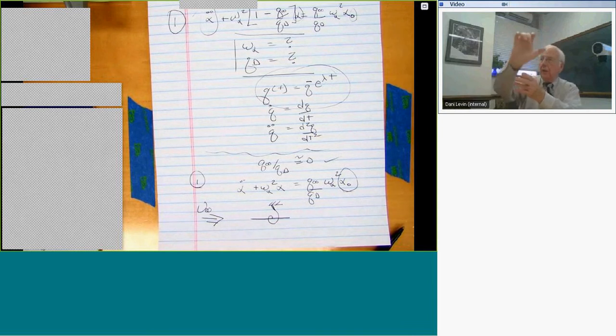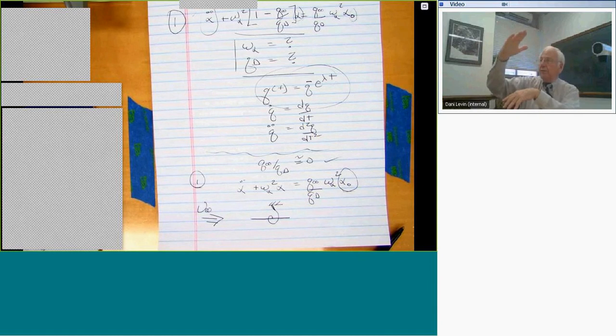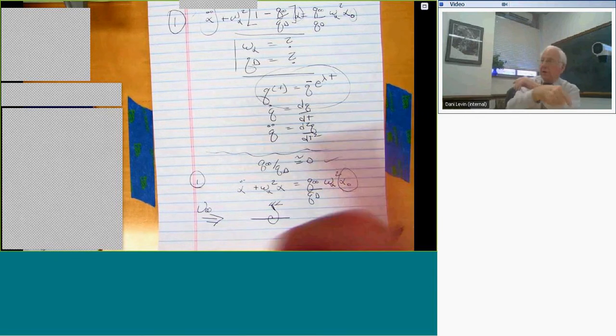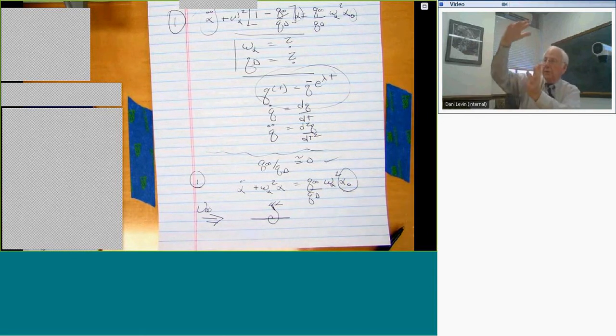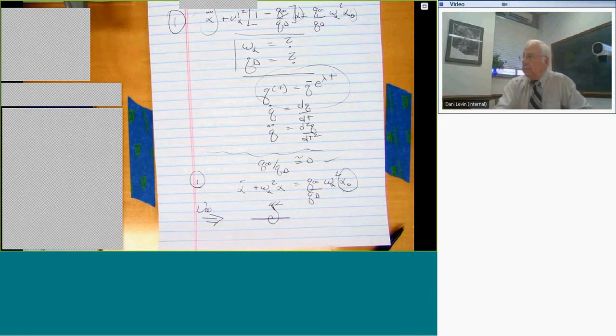And then if there's twist of the spring, the total alpha of this plate relative to the oncoming stream is alpha, the twist of the spring, plus the original alpha naught, which was just the orientation I made. And that's true in a real airplane. When it flexes, there's a rigid body attitude or angle of attack relative to the flow, but then when the thing deforms, there's some additional angle of attack because of the deformation. And in this simple model, we're just distinguishing between the angle corresponding to the spring twist and the angle corresponding to the orientation with respect to the oncoming flow.